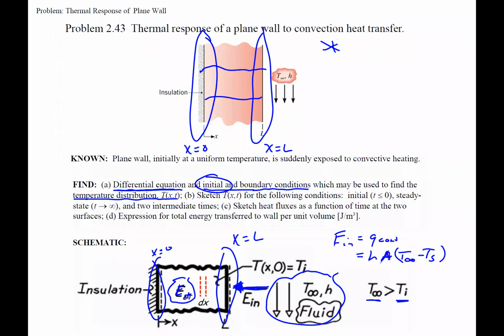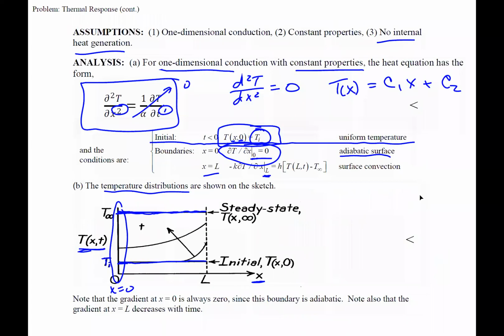Okay, so as we put energy into that wall, the surface temperature is going to increase, and it can only go up to T infinity. So eventually you are not putting in any more energy because Ts is equal to T infinity. So you get a horizontal line then. It's the right side. Basically, we have T infinity then. All the way through, it's the same temperature.